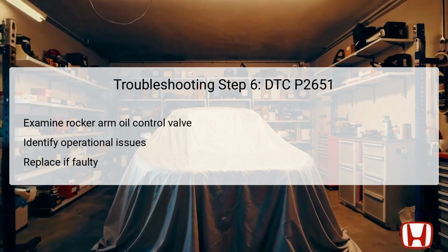If you find that the valve is not functioning properly, it will need replacement to resolve the issue triggering the P2651 code. Ensuring that all components in the VTEC system are operating optimally is crucial for maintaining engine performance.